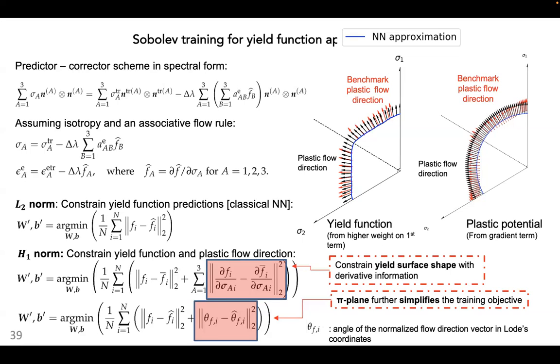You understand what I'm saying? Because if I don't use the actual stress gradient, I use the plastic strain, and then I can still manage to completely rewrite the f equal to 0, and the gradient is also matching the plastic flow. There's no point for me to cook up something that doesn't fit the normal directions. Okay, so I can get rid of the non-associative flow.